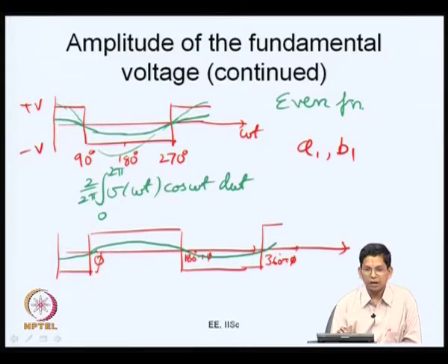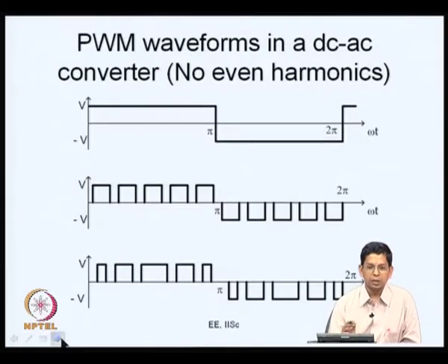When we are not aware of the exact phase, what we should be doing is, we must multiply this by sin omega t and also by cos omega t, get both those A1 and B1 terms, and from there get the overall amplitude from doing it here now. So, this is how you determine the amplitude of the fundamental component.